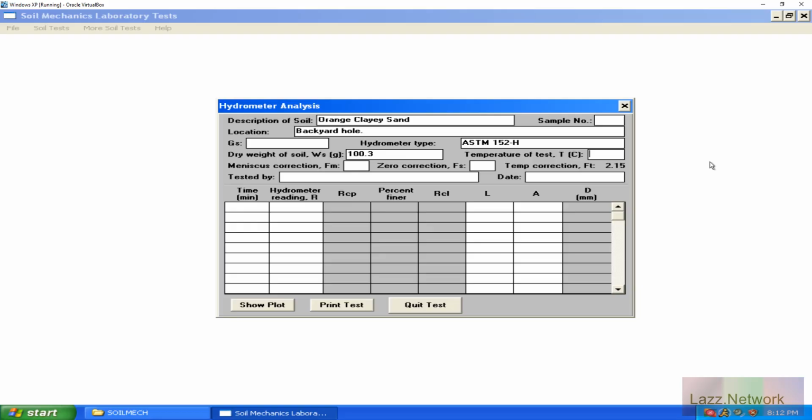So this one here, this is where I say Geosystems is better, because technically in Geosystems you can put in your calibration over time, even inside a building. Fortunately for us for the example, but even if it wasn't on the example I had, this one will only stick to one temperature for your correction, for what the readings you had for your test. That's going to also be utilized for your correction. So for this one, this is 22 degrees Celsius.